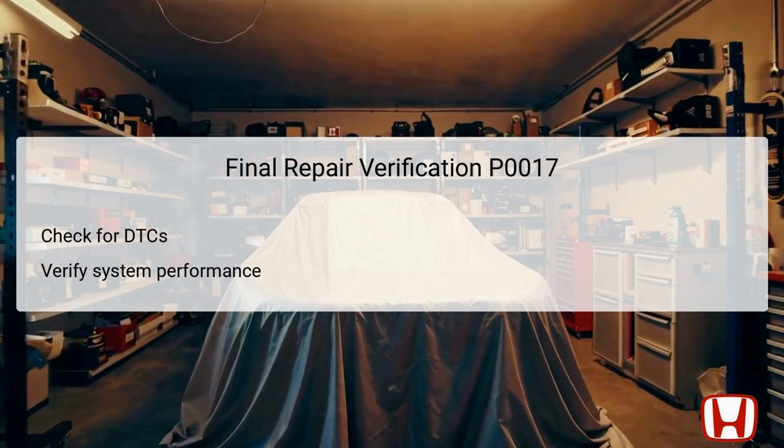Additionally, verify the performance of the VTC system while the vehicle is in operation. It should demonstrate smooth engine performance without irregular idling or acceleration issues. If no issues persist and the DTC is cleared, the repairs can be deemed successful, ensuring optimal vehicle operation and compliance with emission standards.